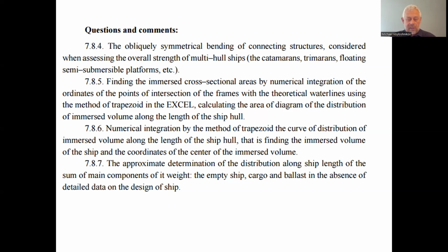So then we can find the distribution of the cargo along the length. We have to find this distribution corresponding the same numbers of the theoretic spacing as we have for the forces of the Archimedes distribution by the theoretic shape of the ship. Then we can find the difference. The difference is the distributed load, non-even and non-equal for the buoyancy. And then for the cargo and for the load, distributed gave us different differences.